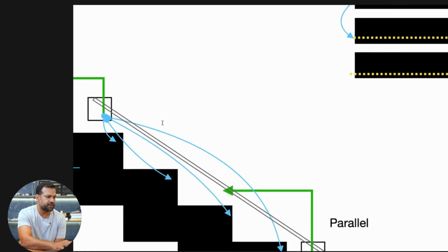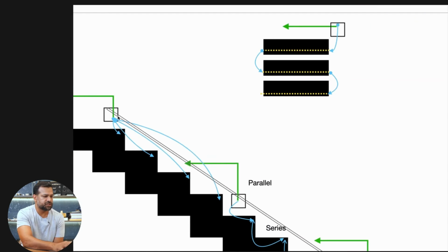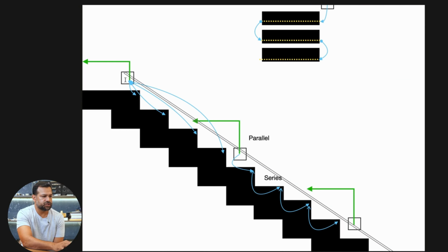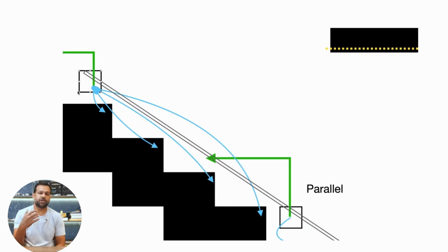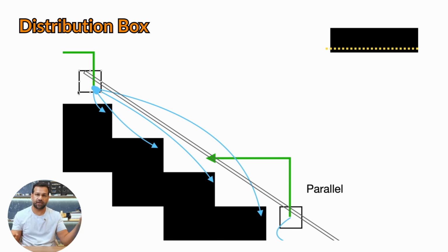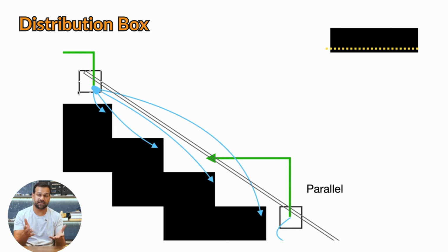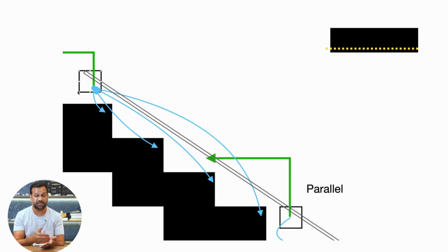Now, if you're using a non-motion sensor LED, there are two ways you could approach it. The first way is having just a few electrical junction boxes like this, and you can treat them as a main distribution box. So you could have a thicker gauge wire coming into that box and then use smaller wires, because it's easier to work with smaller wires, from 18 gauge all the way to 22 gauge, to get those details into the stairs.